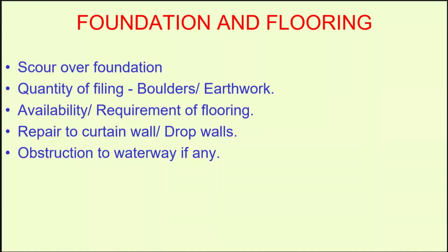And again, in the flooring system, we put stones so big that they cannot be easily lifted by the water forces, the scouring effect, and settled and lost somewhere. So you should have sufficiently big stones and a sufficient area covered.